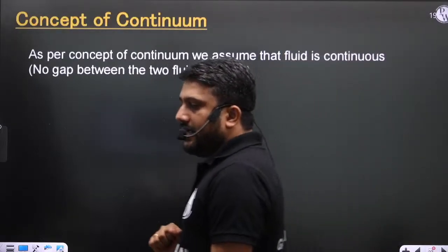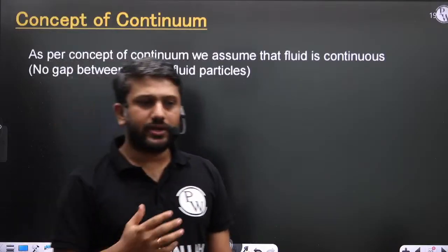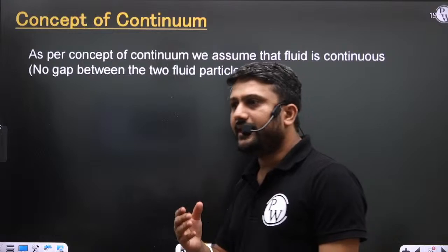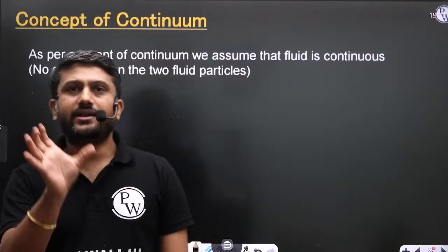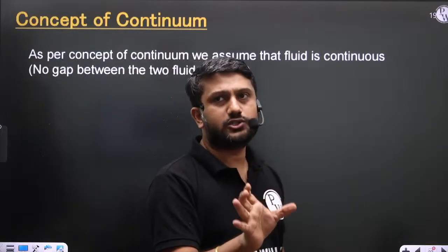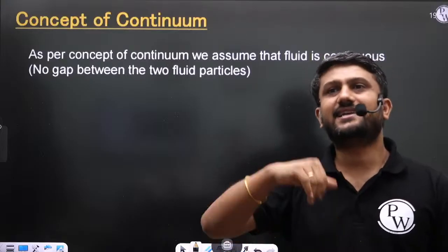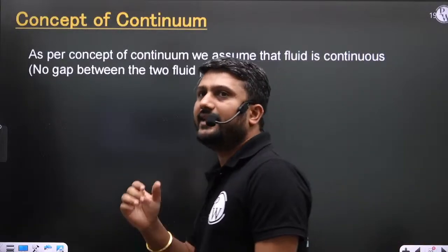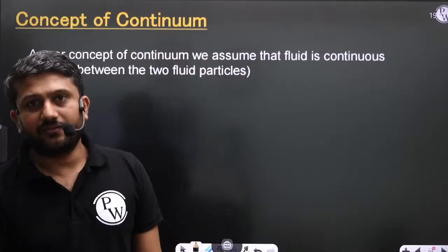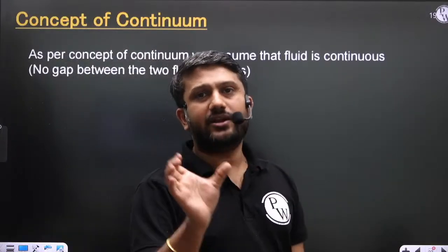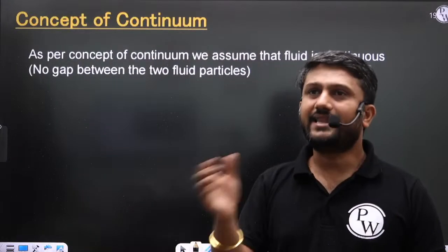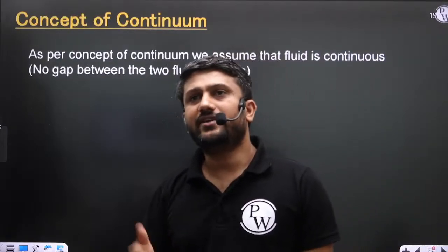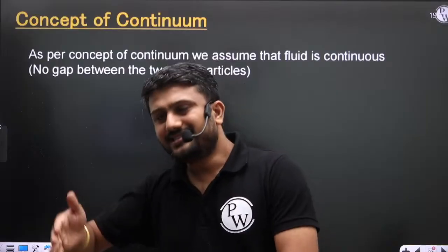Now, in the concept of continuum, we assume that the fluid is continuous. That means the interatomic distance between two molecules of the fluid we consider negligible. The gap between two fluid particles we assume is negligible. We can assume no gap between the two fluid particles. That means the fluid is continuous.